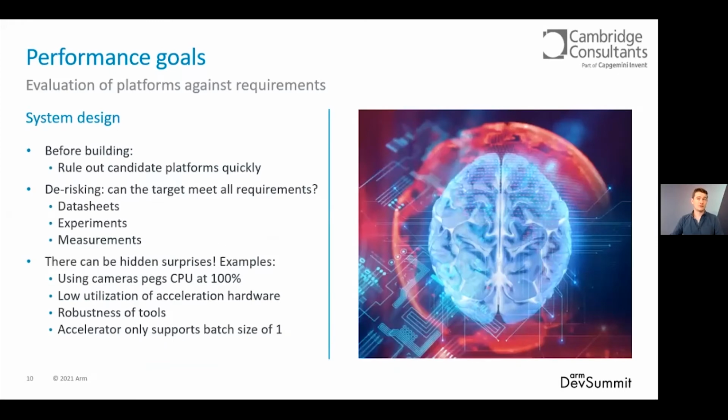Once a concrete set of requirements has been collected, the Edge AI platform must be selected. The huge variety of hardware and software offerings for Edge AI in the marketplace today means there often is a solution that will work, but the key question is which one to choose. Ideally, we want to rule out candidate platforms early and with the least time spent doing so. To do so, we have a few options in roughly ascending order of difficulty: matching key requirements up to datasheets, obtaining an evaluation kit to run software experiments, and finally doing hardware-based measurement of metrics such as power consumption.